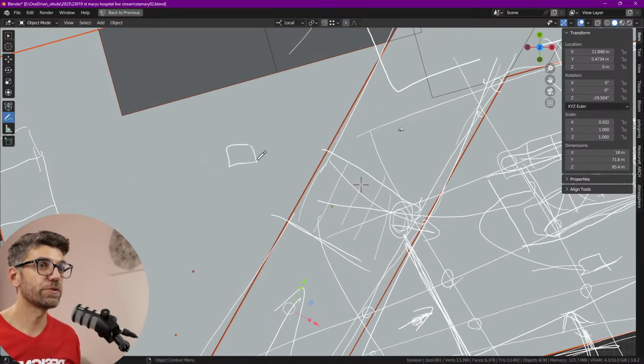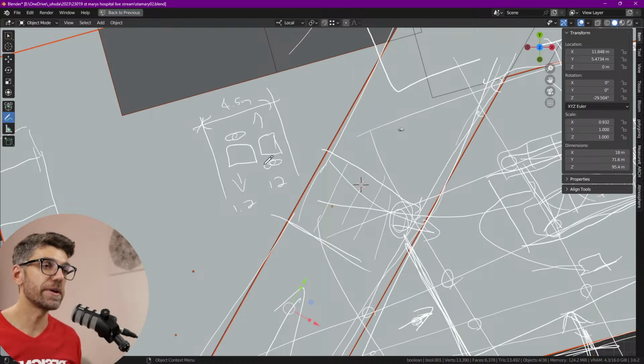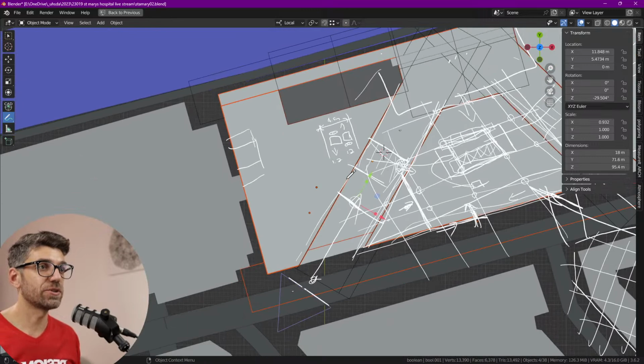So two people with wheelchairs and the person behind them can move in both directions, right? So that's the least amount of width that we need in there. And that's not too much when you think about it. You need like 1.2 and 1.2 meters, but ours should be at least 4.5 meters tall. However, we want to keep that distance to a minimum because if it's too big, then we're going to block too many views. Imagine having a really, really chunky bridge here, right? Then we're really losing that connection that we're trying to create there. So we're going to try 4.5 meters and see how that works.